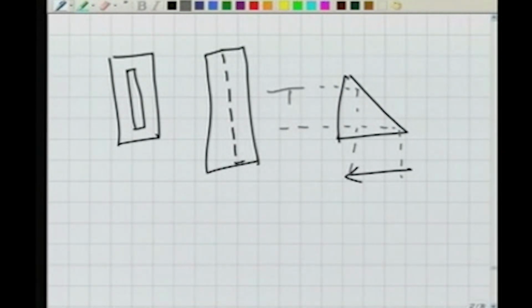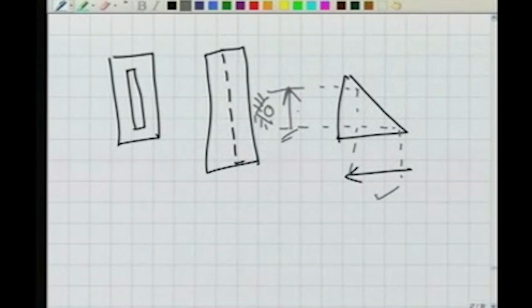It will be reflected like this, and this is how it will be seen. So the role of the prism is to invert these graduations, because my eye is here. We make the graduations inverted in the circle down there so that we can see them erected. So the prism erects those inverted graduations.